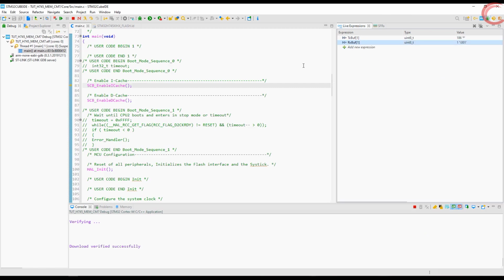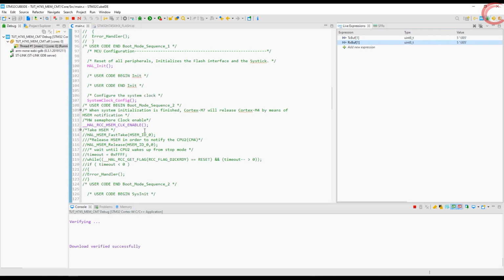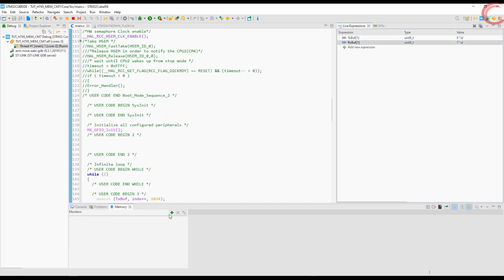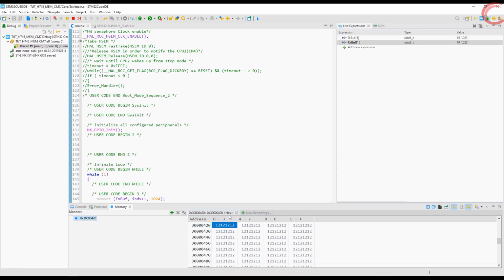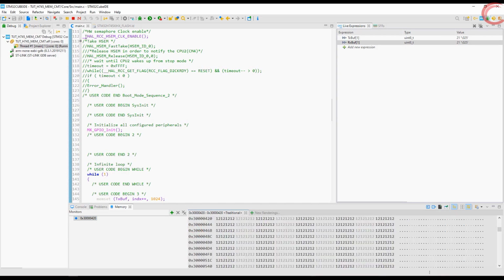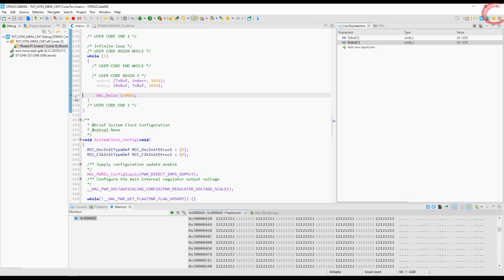Here I am using only one element of the array, since all of them will have same data anyway. The data is updating every second in both the buffers. Let's check the memory locations now. This is the memory location for the RX buffer, and you can see the data here. It's also updating when the new data gets copied from the TX buffer.